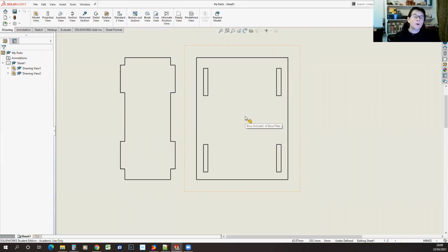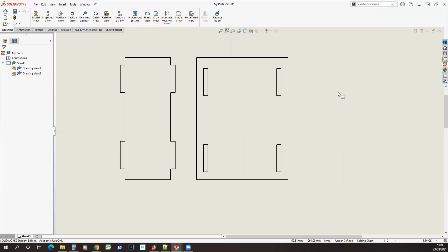The problems come when you realize that your 3mm acrylic sheet is actually cast acrylic. And the way they make it is they basically pour a load of liquid acrylic onto a big flat bed so that it kind of pools up to 3mm thick. And then they let it cool until it sets into a nice sheet of acrylic. But there's surface tension on the surface of that liquid acrylic.